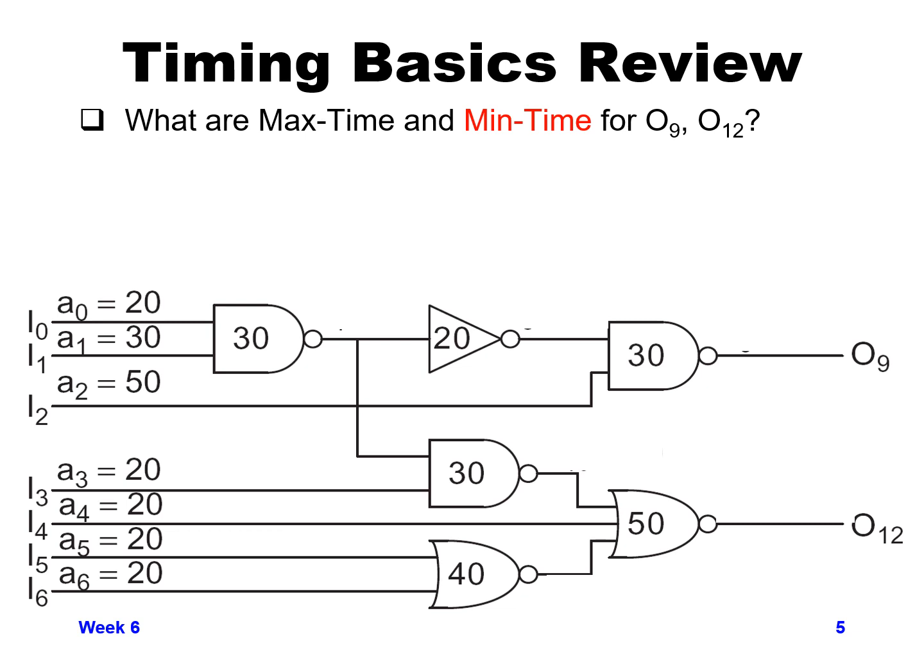So A0 is coming in at 20 picoseconds after our reference clock. A1 is 30 picoseconds. A2 is 50 picoseconds after that reference clock, etc. The gates themselves, so these NAND gates, NOR gates, and inverters, the amount of time for the delay through each gate, so the time from the input switching 50% to the output switching 50%, is the number provided on the gate itself.